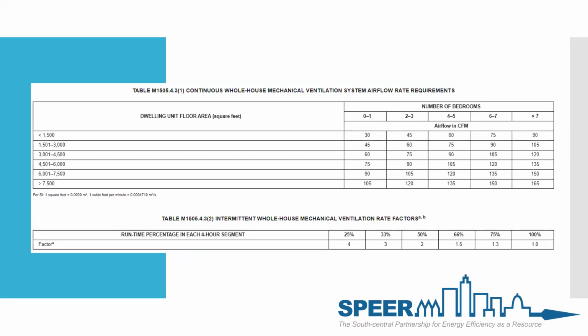Those systems can run without conditioning. So it's just the fan turning and it's pulling outside air in. It could be 100% humidity, and that's what's being pushed into the home. So with that, sometimes that can lead to additional problems because you have a tight home, you're building up humidity. We're seeing this a lot in foam houses and just homes being built a lot tighter. It's building up more humidity inside the house, which leads to additional problems that we'll discuss later in the webinar.